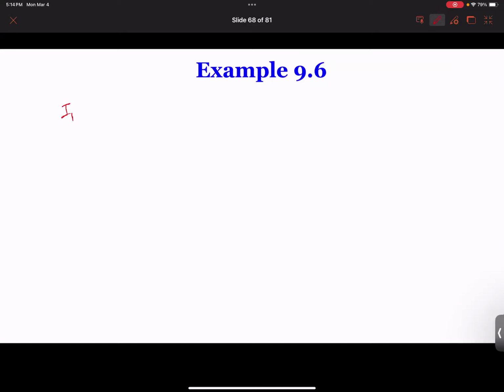So we know that I reference was given at 100 microamps, VT was given at 0.5 volts, and VA was given at 5 volts. We use this absolute value because there's P-type and N-type. For N-type, it's a positive value, for P-type, it's a negative value. But when you do the calculation, it's the same thing. So you just use the absolute value to make it easier.